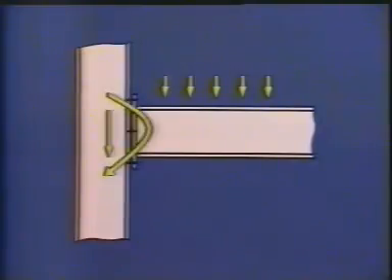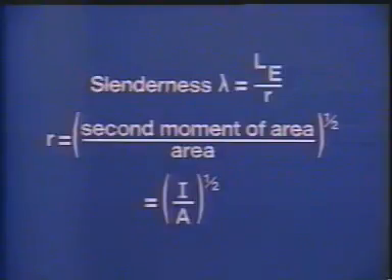Because the primary role of the column is to carry the vertical loading to the foundations, the governing force in the section is usually axial compression. This is often accompanied by moments transmitted from the beams, produced by beam bending. The response of a column to applied compressive loads depends on the column's slenderness, related to the length of the column and its radius of gyration.